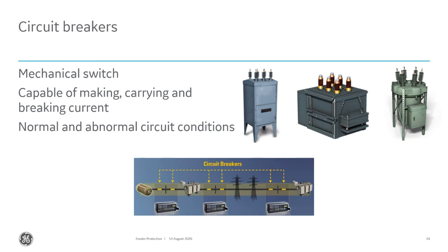So there's no reason you have to have a lockout relay, and most of today's world has gone away from the lockout or auxiliary relay. They've gone towards tripping directly from the microprocessor, and we refer to that as a virtual lockout. The lockout function becomes part of the coding or the logic of the relay, and that's why we call it a virtual lockout.